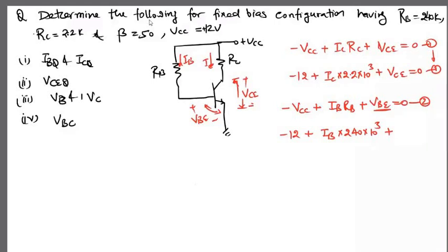If the transistor is working in the active region, the value of VBE will be 0.7 volt. Keep this in your brain forever. In any region, if any junction is forward biased, in that case that voltage will be 0.7 volt.